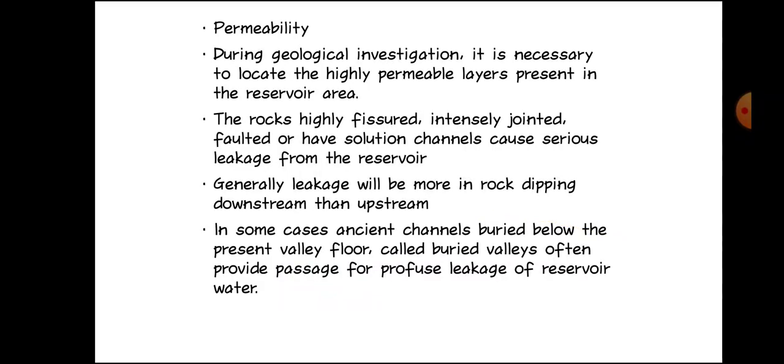Permeability. During geological investigation, it is necessary to locate the highly permeable layers present in the reservoir area. Rocks that are highly fissured, intensely jointed, faulted, or have solution channels cause serious leakage from the reservoir. Generally, leakage will be more in rocks dipping downstream than upstream. In some cases, ancient channels buried below the present valley floor, called buried valleys, often provide passage for profuse leakage of reservoir water.